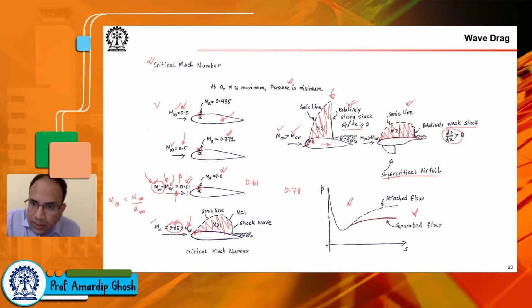Now, because of the flattening of the top portion, it can be shown that the camber in this front part of the wing becomes negative, and that reduces the lift at some angle of attack. So to compensate for that loss of lift, the rear portion of the wing actually has a very high, or rather positive, camber ending in a cusp. And it has been seen that for these kinds of wings, you can actually push your critical Mach numbers to 0.8 or even beyond that.